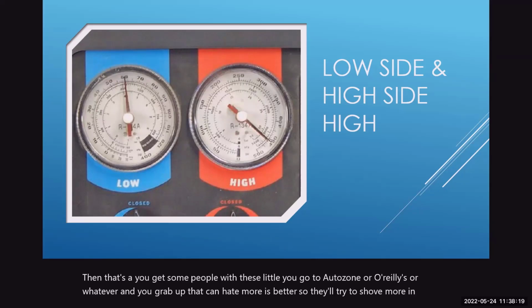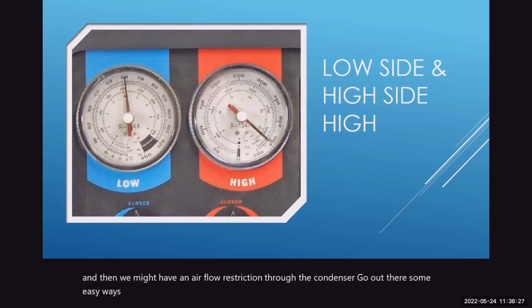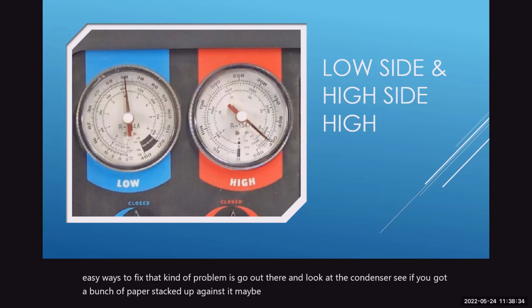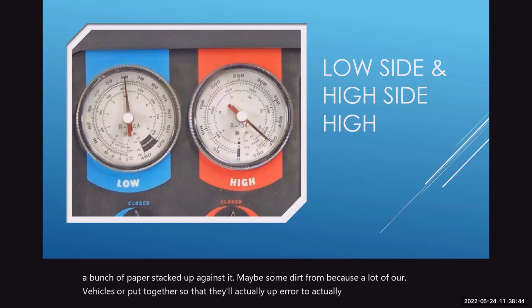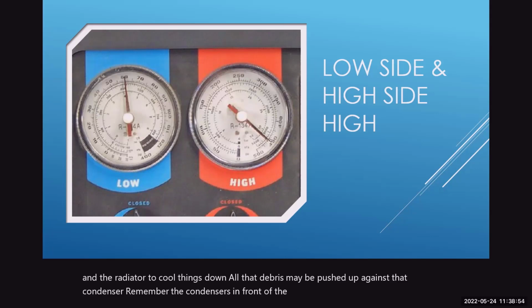And then we might have an airflow restriction through the condenser. Some easy ways to fix that kind of problem is to go out there and look at the condenser, and see if you've got a bunch of paper stacked up against it, maybe some dirt, because a lot of our vehicles are put together so that they actually scoop up air to go across the condenser and the radiator to cool things down. Well, all that debris may be pushed up against that condenser. Remember, the condenser's in front of the radiator in most cases.